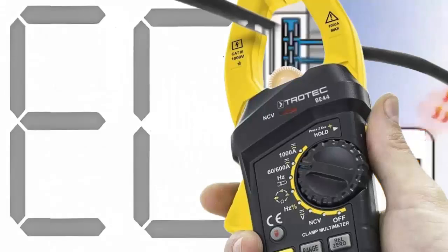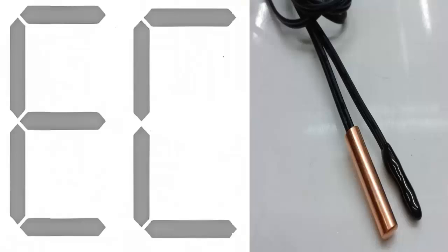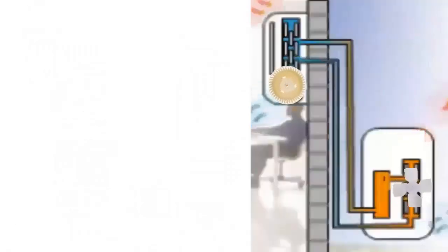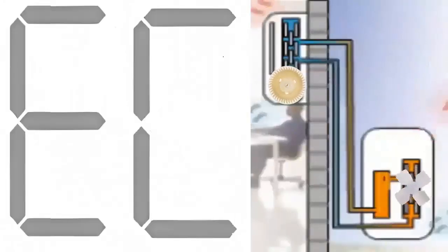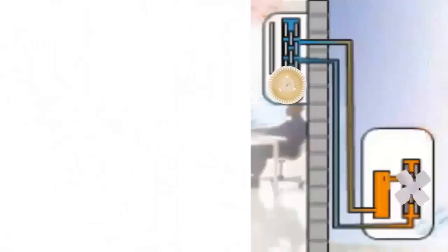D. Check the temperature sensors. A faulty sensor can trigger this error. E. Repair the leak and recharge the system with the appropriate refrigerant. F. Ensure that the refrigerant pressure is correct.